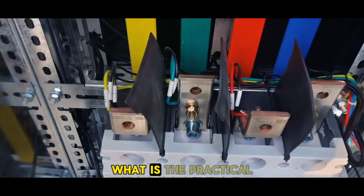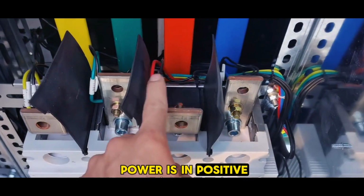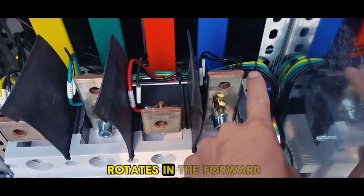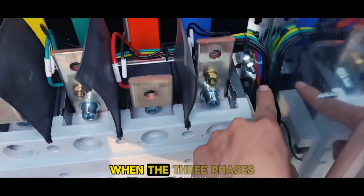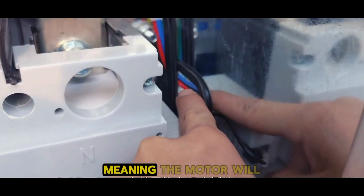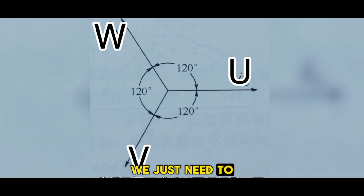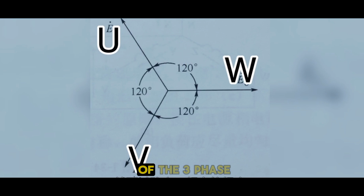respectively. What is the practical use of phase sequence? If the three-phase power is in positive sequence, the three-phase motor rotates in the forward direction. When the three phases are in reverse sequence, the motor will rotate in the opposite direction, meaning the motor will reverse. If the motor is running in reverse, how do we adjust the sequence? The method for adjustment is very simple. We just need to swap any two phases to change the sequence of the three-phase power.